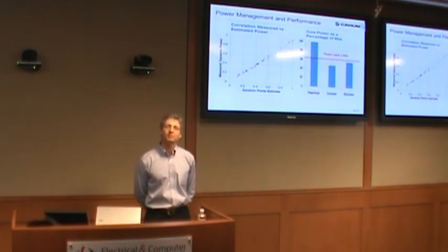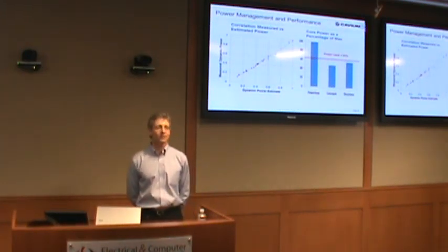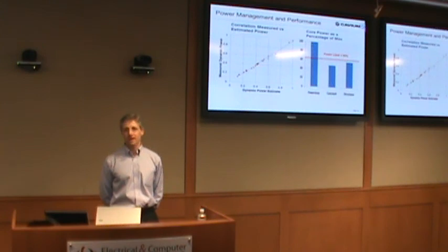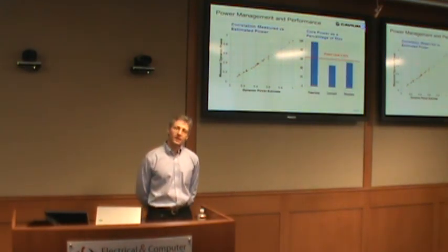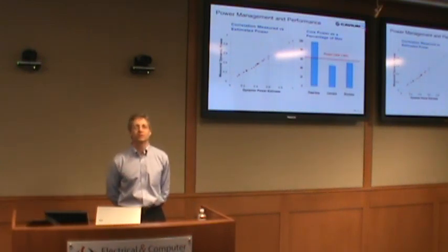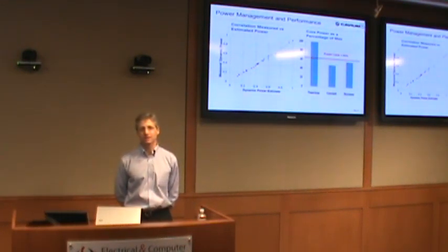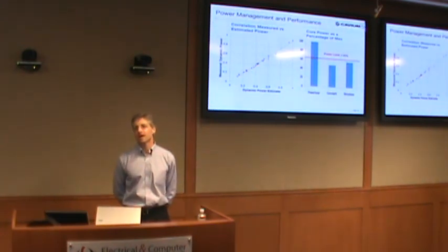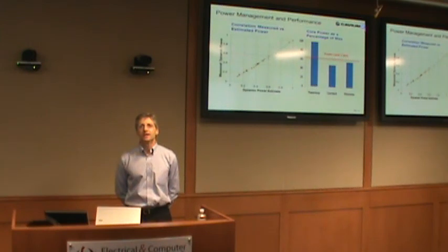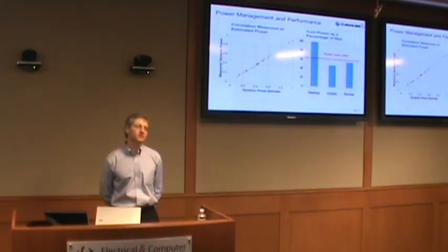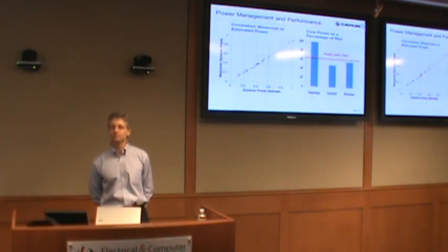And you'll notice there aren't very many things up in that upper right corner. And that's what the right graph is showing us also. In the right graph, we show the power as a percentage of max of our power virus. The power virus is our worst-case one. And what you might consider typical applications, like there's a benchmark called CoreMark, or there's the Dhrystone benchmark, or insert your favorite benchmark. The idea is that most applications don't come anywhere near consuming that 100% of the power.